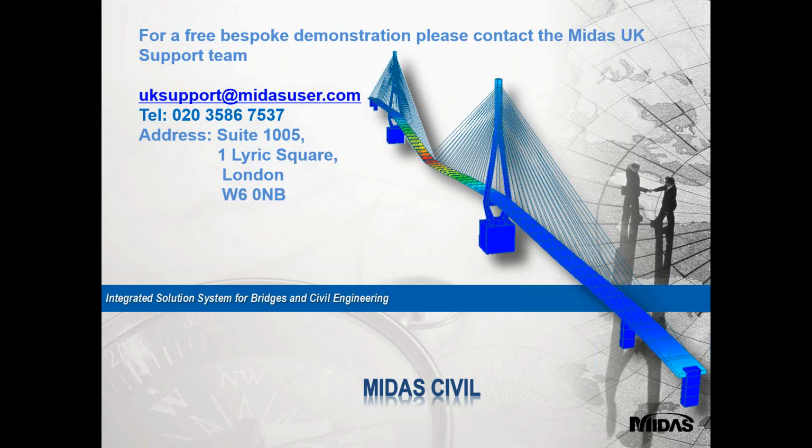One of the attendees has also asked if scaled eigenmodes can be used for both global and local shapes in Midas. The scaled eigenmodes are entirely based on the buckling mode shapes. So if you have modeled all your elements properly in the full finite element model, then you get the buckle shape of the entire model, including all the local elements and also the global line elements.